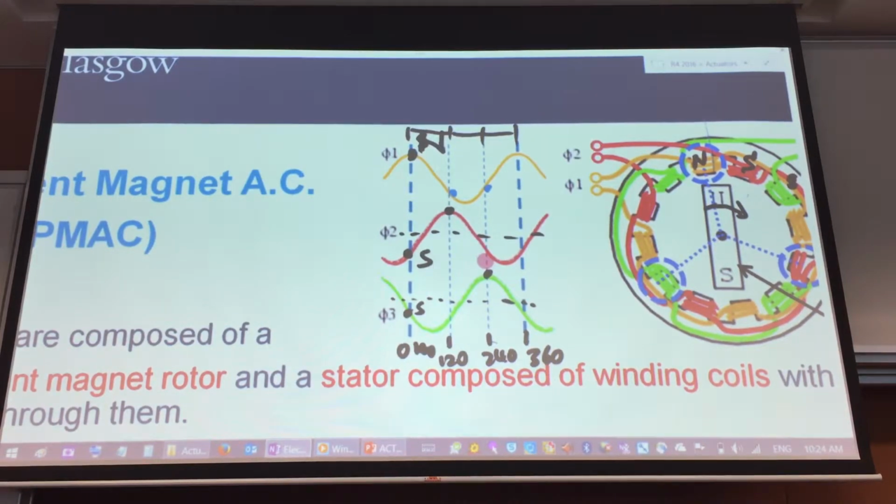And the rotor will rotate at a rate of 1 to 3% less than that speed. Because it's not a physical gearing system that will rotate the shaft, but using magnetic forces to repel and attract.